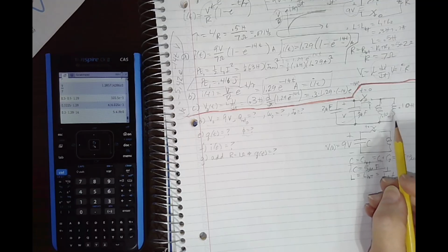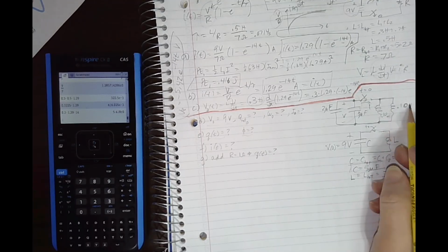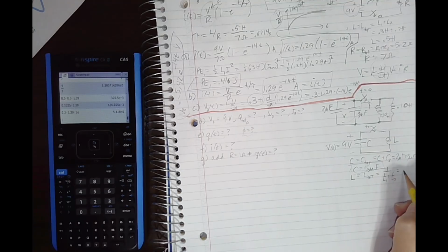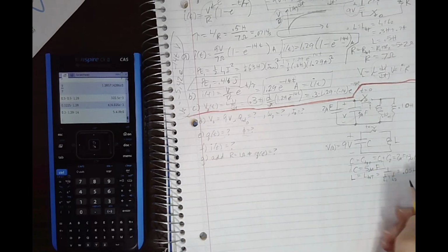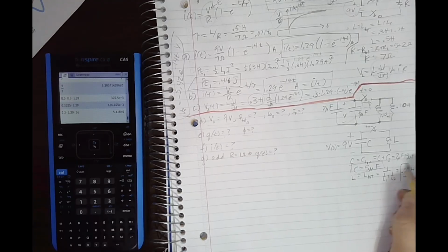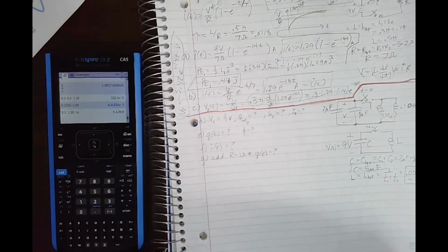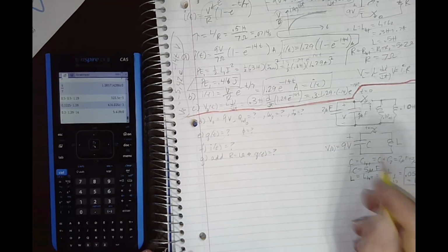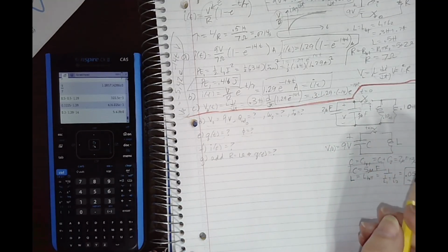Luckily, me being lazy, I made both the inductors the same size, so when you have both things the same size in this equation, we just get the answer being a half, so it's 0.05 henries would be the total inductance. Plug it in your calculator if you don't believe me. Okay, and so we've got our parameters for our circuit here.